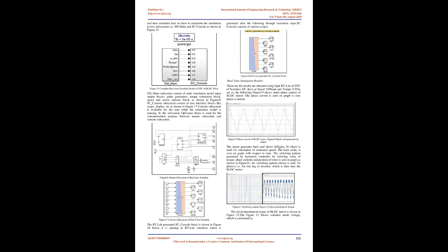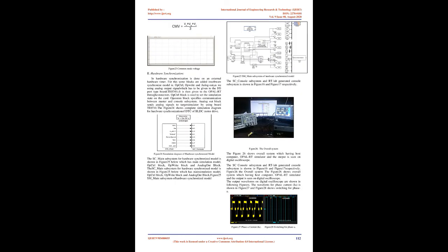The RT-LAB generated SC_console block is shown in figure 18 below. It is running in the RT-LAB simulator, which is generated after the following execution steps. SC_console consists of various scopes. Figure 18: RT-LAB generated SC_console block. Real-time simulation results: these results are obtained using Opal-RT Lab for DTC of brushless DC drive at speed 1500 rpm and torque 0.5 newton-meters.